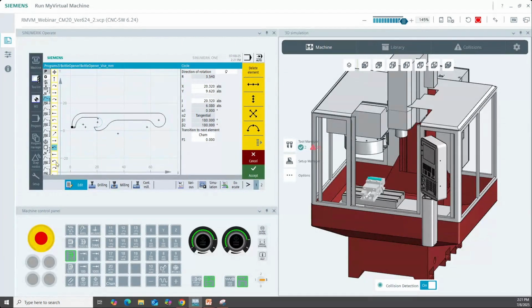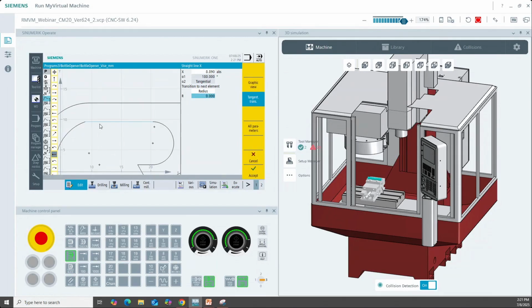What I think we should do is go to the next element and go to its radius. This is what's called an end of line function. Basically, at the end of the line, I can say, hey, I want you to blend a radius or a chamfer into whatever comes next. So even though I have an arc coming next, it's smart enough to allow me to blend it. So that's a 4 mil radius.